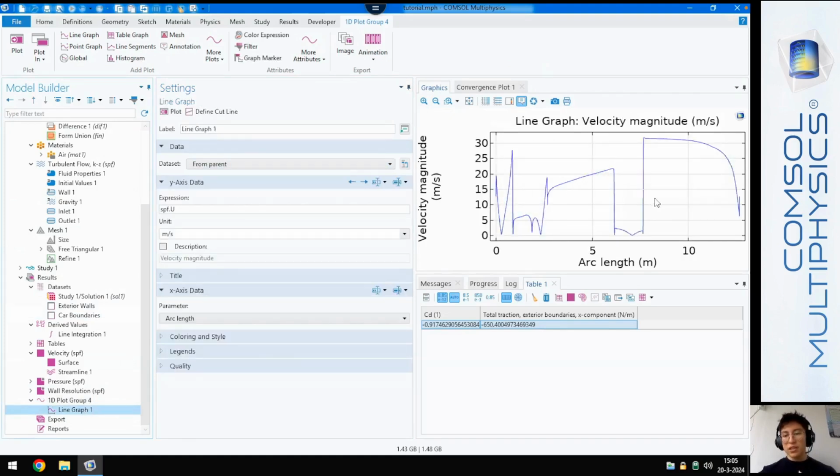And here what we can see is that COMSOL has generated a plot, and this is just the velocity of the air particles on the boundaries. But this is not something that we care about. So the first thing that we should do, that we're going to plot actually, is the total stress. So let's give this a nice little label, total stress. And what that means is that the expression that we're going to evaluate is going to be spf.T_stressX, just as we did before.